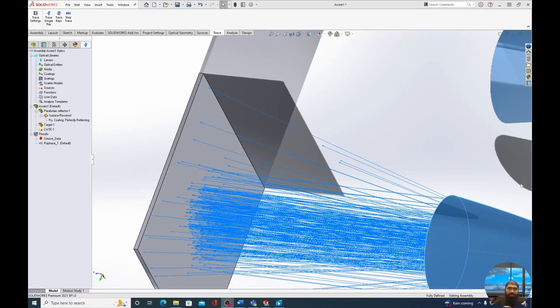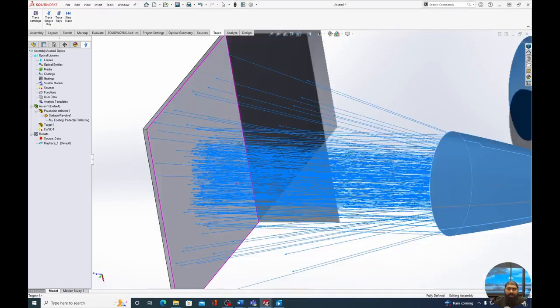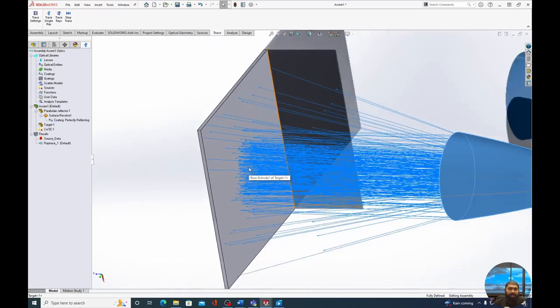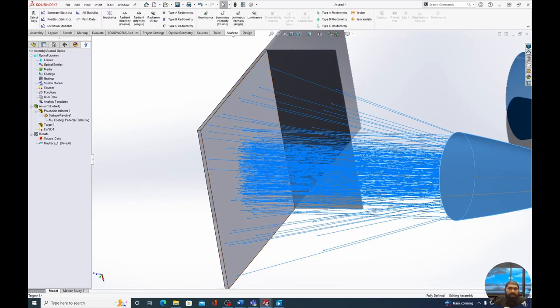However, as much as we enjoy looking at these very beautiful rays that APEX produces, the value in this is in analyzing the property of the scattering and the incoming angle of the system. So here we will go to our Analyze tab, and we will look at the irradiance and radiant intensity. The irradiance will see how much light is in any given square pixel of the grid that we choose, and the radiant intensity will let us see the angles of incidence, or the angles in which the incoming light rays